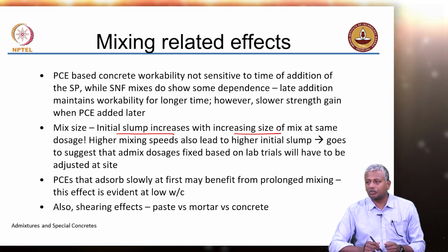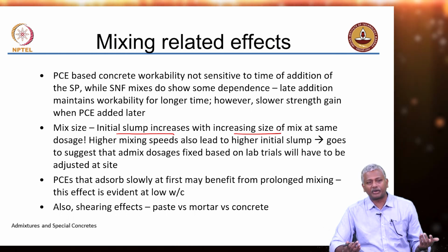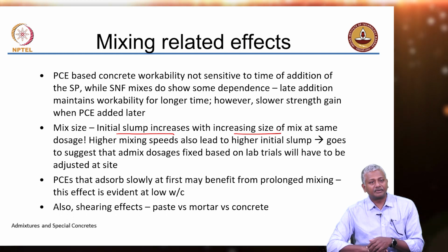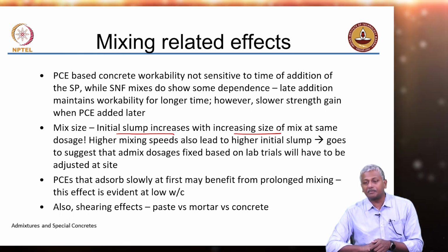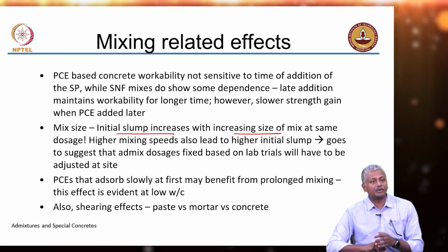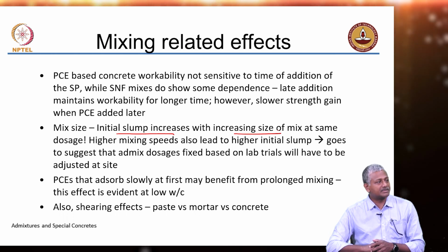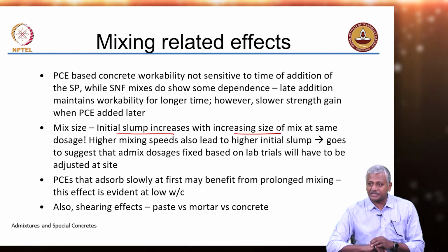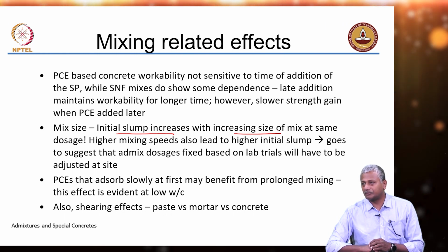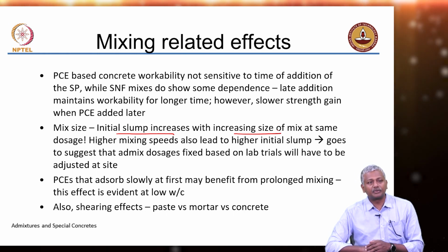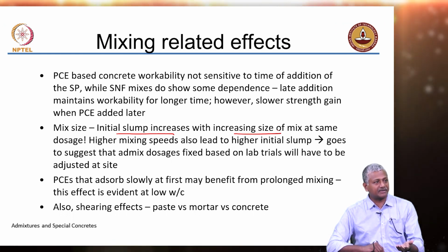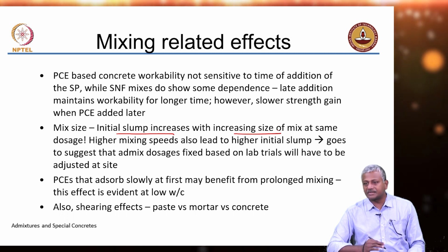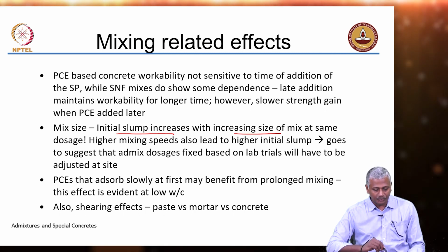Compared to this, when you start mixing in the RMC plant, which is 0.5 cubic meter or 1 cubic meter, right, in such cases, the difference in the mix characteristics can be significant. I'm not saying will be, but can be. So, whenever you have a mix design that is tested in the lab, always follow it up with a field test. It is an absolute requirement to do a field test also of the same.